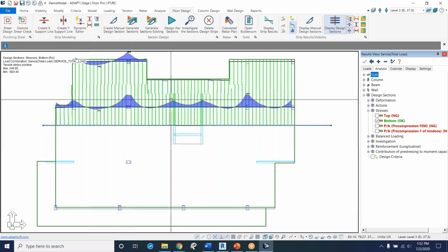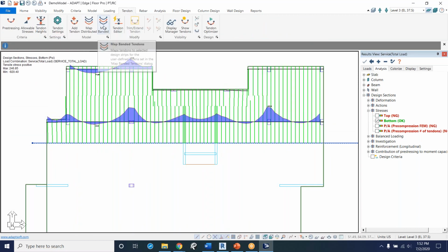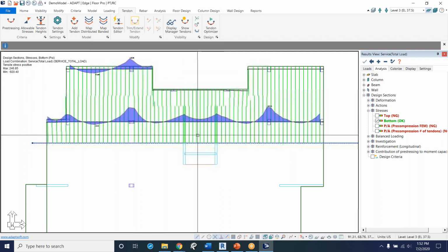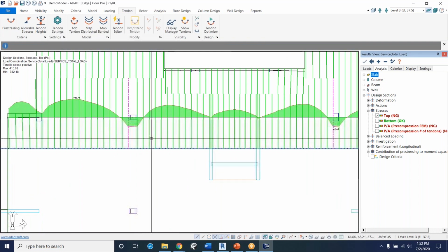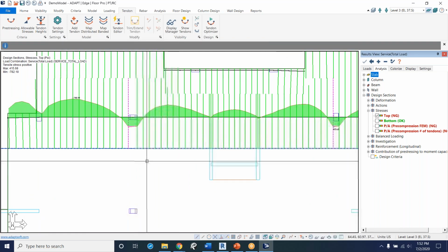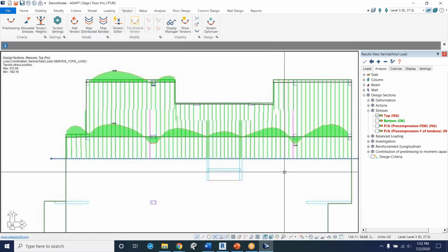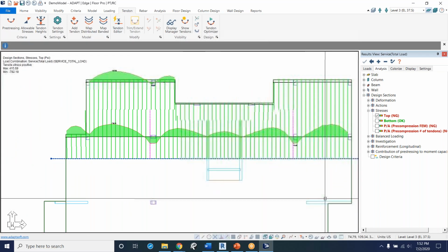And here you can see, hey, look, our bottom stresses are good. So the amount of tendons that the program picked for our banded direction, just based off of the support line, was pretty close, but let's see what the top looks like. You can see, okay, we have a little bit of stress issue here. Now we haven't checked this for punching shear. We could do that because maybe these columns actually need to be increased in size, and that may have been a more logical step to go about doing before this. So let's see what our punching shear looks like. Let me clear the display.